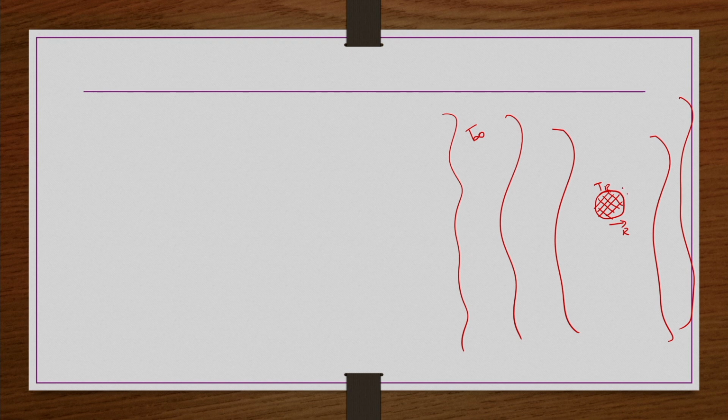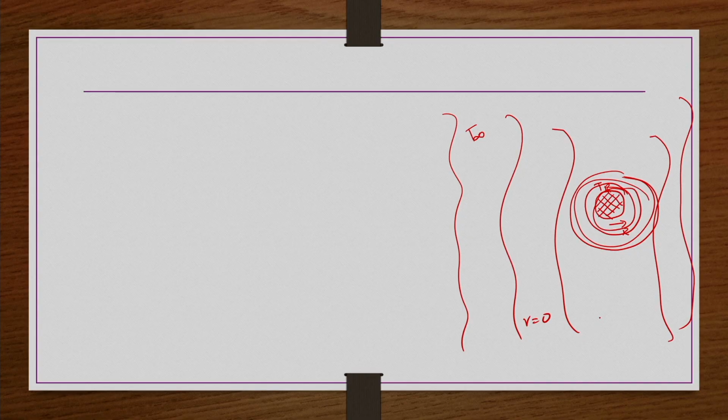So, heat transfer is taking place to the surrounding fluid, in this manner, because of conduction. Why conduction only? This fluid is stagnant, motionless. Stagnant in the sense V is 0. If V is 0, all the convection terms on the left hand side of the energy equation will be negligible.